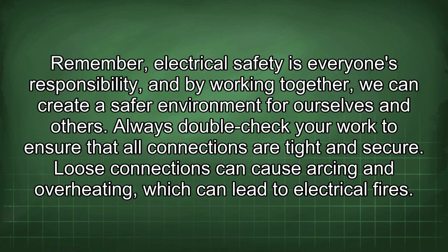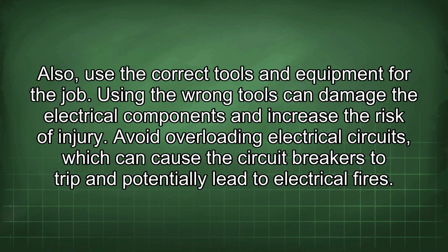Always double-check your work to ensure that all connections are tight and secure. Loose connections can cause arcing and overheating, which can lead to electrical fires. Also, use the correct tools and equipment for the job. Using the wrong tools can damage the electrical components and increase the risk of injury.